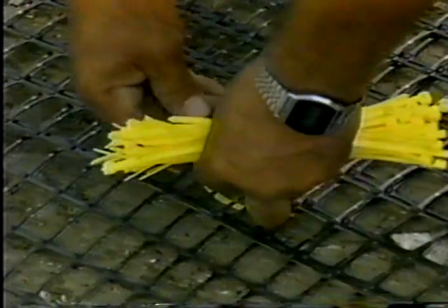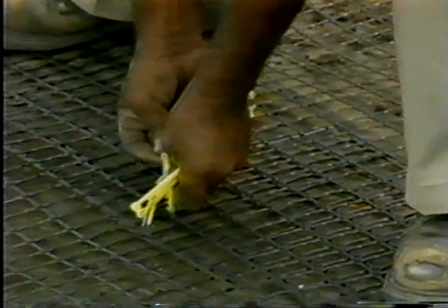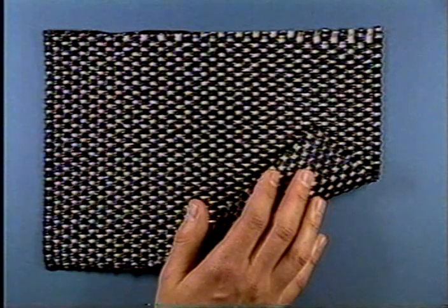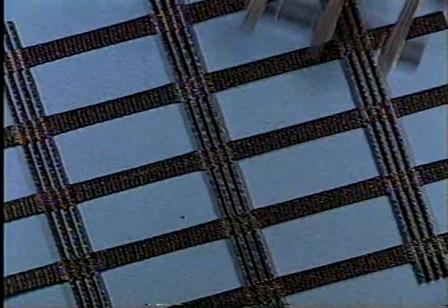As reinforcement, geogrids and some specialized geotextiles add tensile strength to the soil's compressive properties in much the same way as steel is used to reinforce concrete. Specialized geotextiles provide high tensile strength. Geogrids provide high tensile modulus and interaction with the soil.